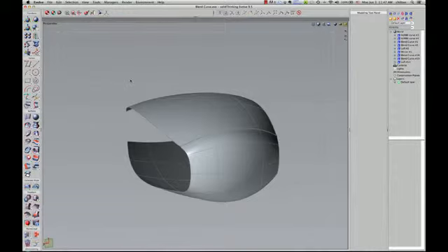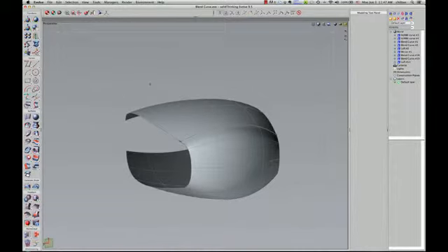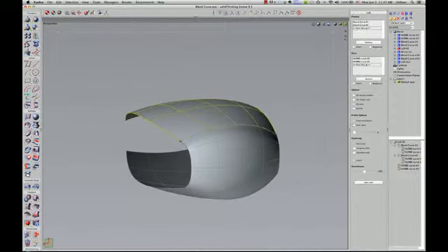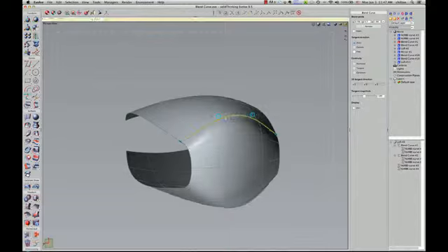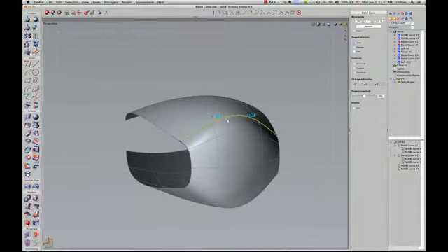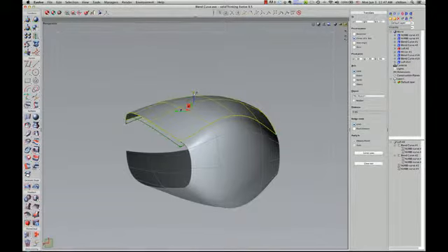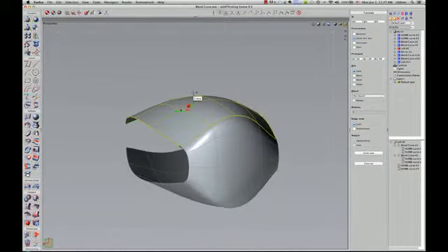So looking at this example, I can choose any part of the model, whether it's a curve or a surface. So I'm going to choose the blend curve, and I'm going to move that blend curve up or down, and you can see that all the surrounding surfaces automatically update. And the same happens if I choose directly on an object itself and change its position. The model continues to update.